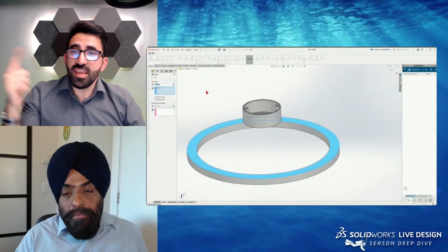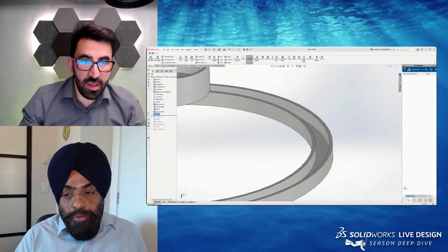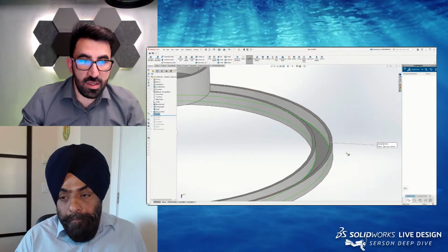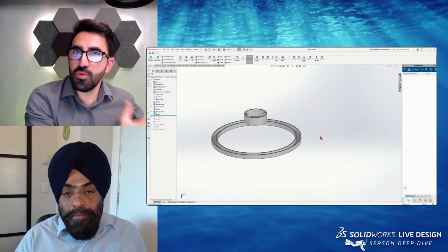But that's not all. The other factor is I have to choose what kind of strip light I'm using here. So after choosing the one you want to use, maybe you have it, maybe you want to buy it, you have to find out the dimensions. So this one is 10 millimeters wide and 6 millimeters in height. Let's just call it the height. So I need to take that into account. When I shell this, do I have enough room here? Do I have enough space to place this strip light here? So yes, I do, and the height is okay, and the thickness for the 3D printer is okay.